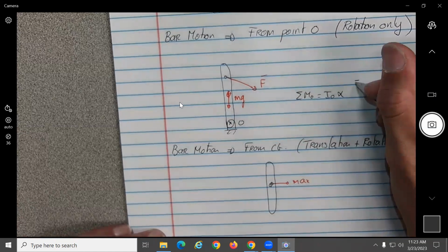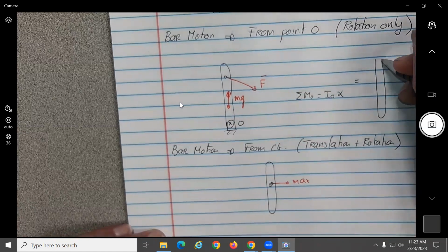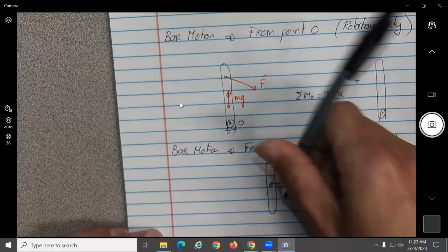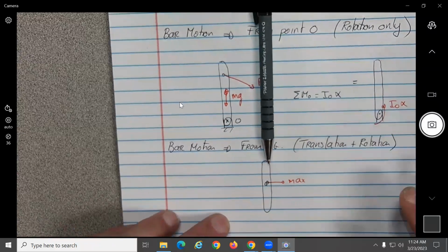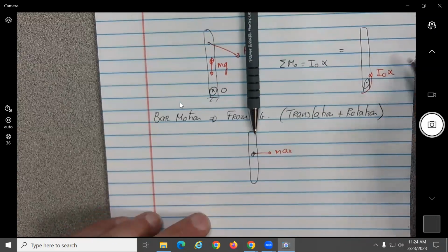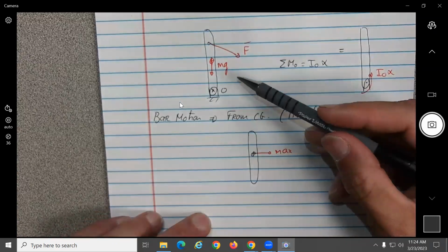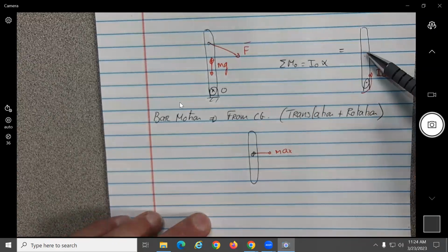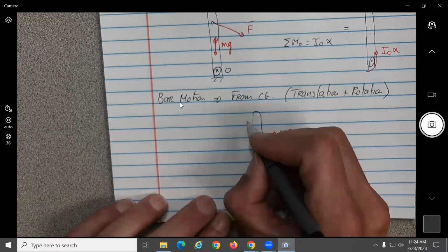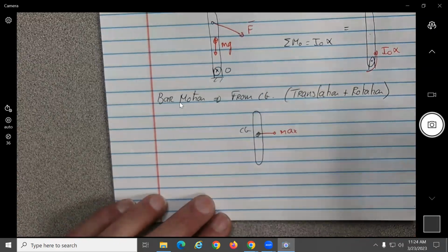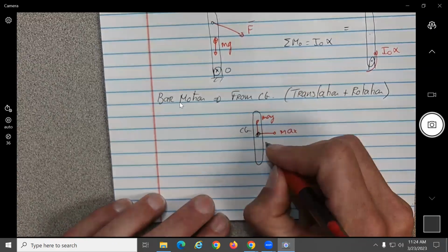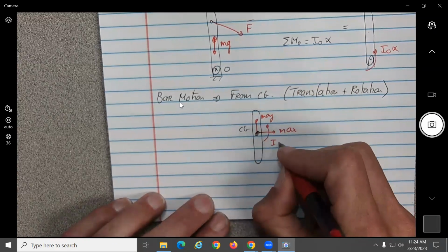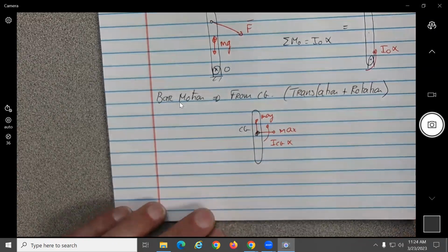Remember, you always need to do two figures. So if you do from point O, then you will have only this. All right? Because when you use the polar system to move it from here to here, you're moving all the actions that happen here to here, no? All the accelerations. Okay? If you keep the CG here, you're still going to have MAX, MAY, but now this will be I_CG alpha.